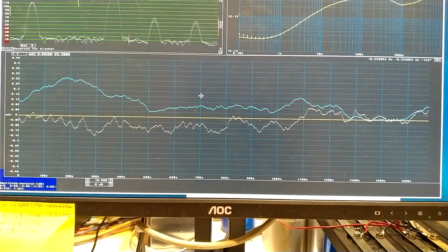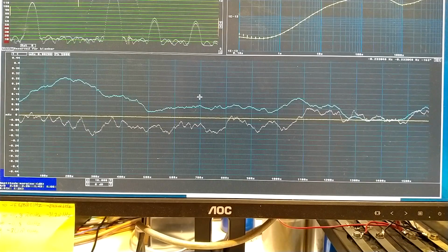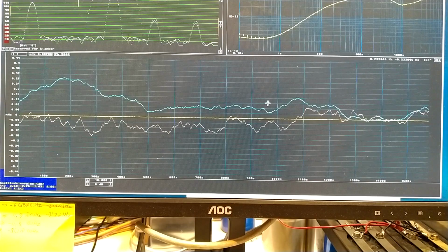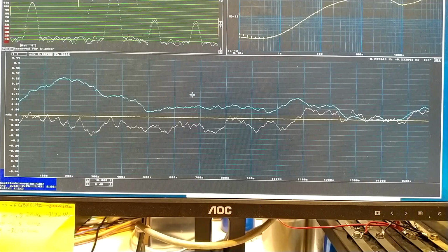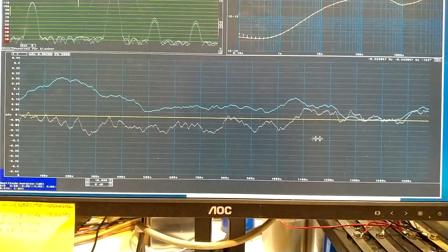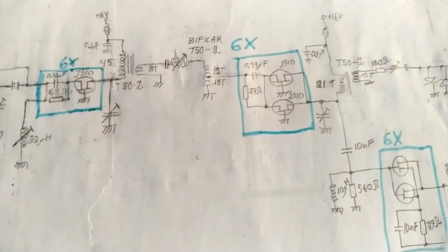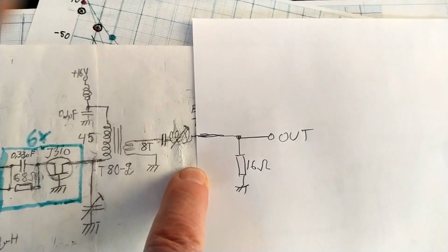There are amplifiers in the two-channel receiver, both on the oscillator side and on the RF side. And there are frequency mixers and other things. And all have a phase shift, and it varies with temperature. Here I can think this is temperature. I have disconnected this amplifier also, like this.